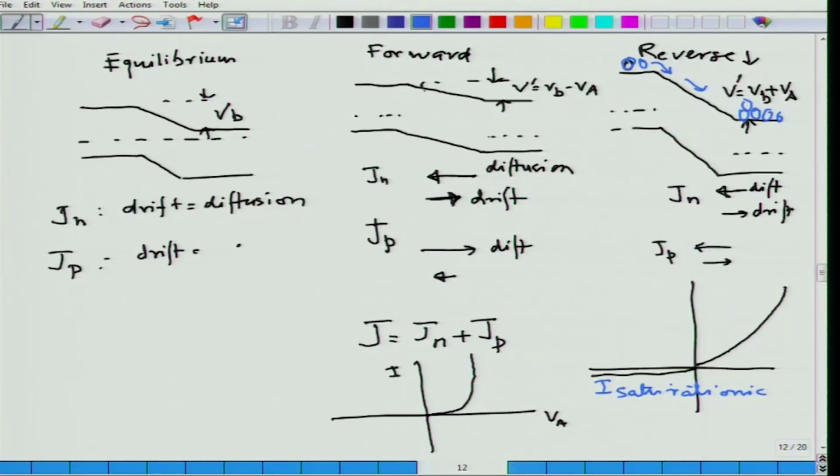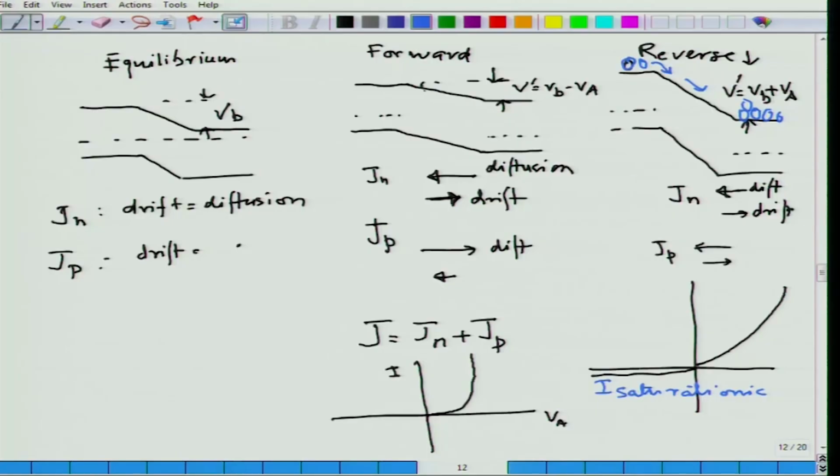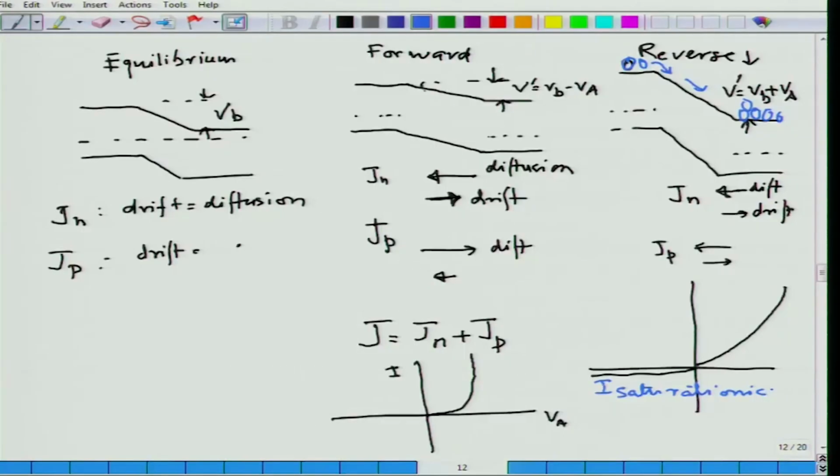And so, in this sense we have a simple p-n junction. We just used a material, and because of the property of the material, it develops a built in potential. Now, we apply a voltage to it. If I apply positive voltage, I get a huge current, and this is because the built in potential gets reduced. If I apply reverse bias, I have more bias and the current substantially gets reduced, and that is a very small amount of saturation current. And this is basically your diode.